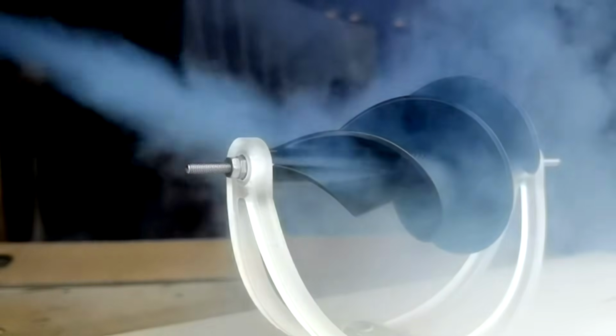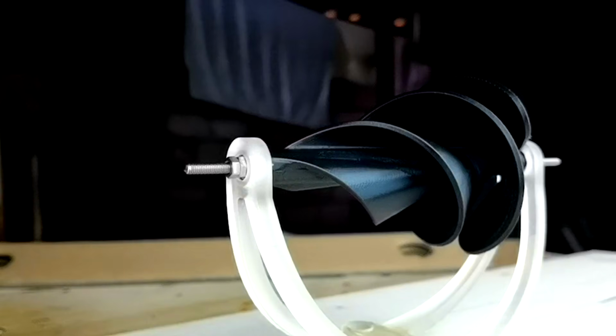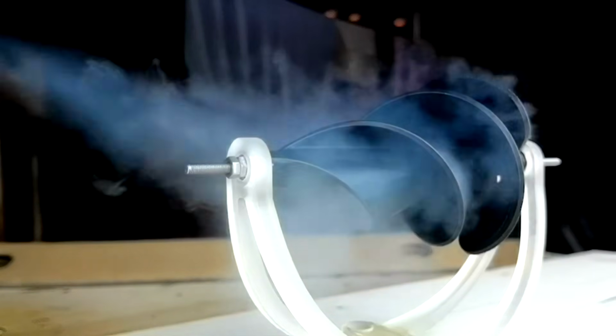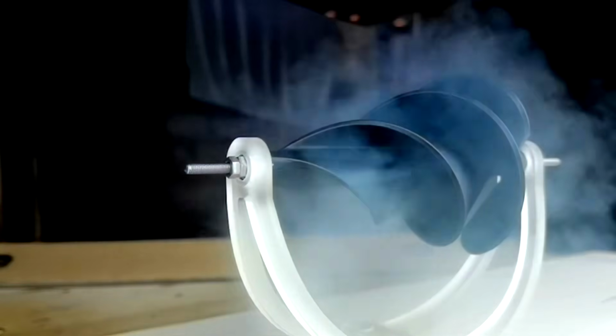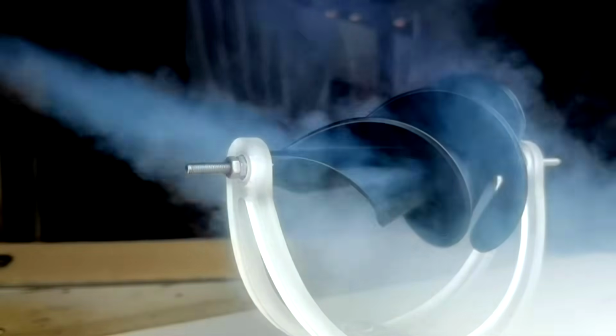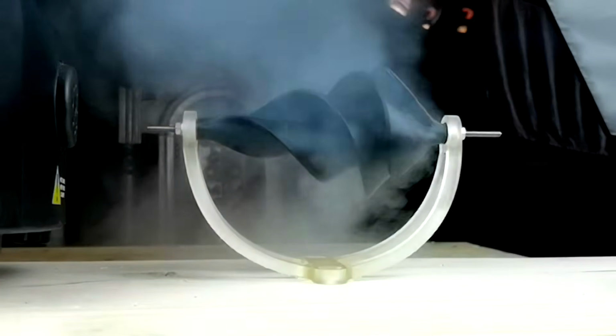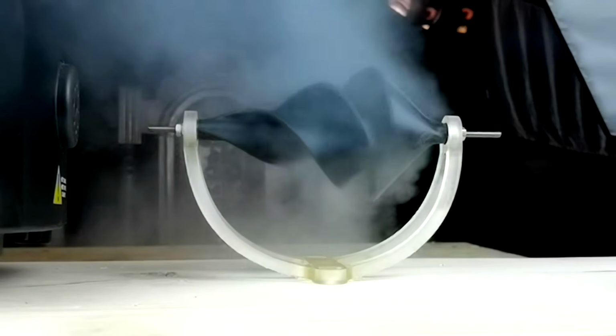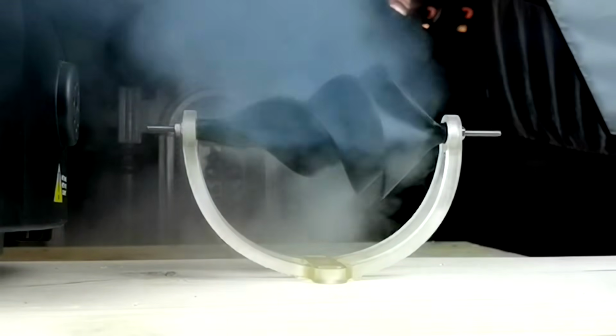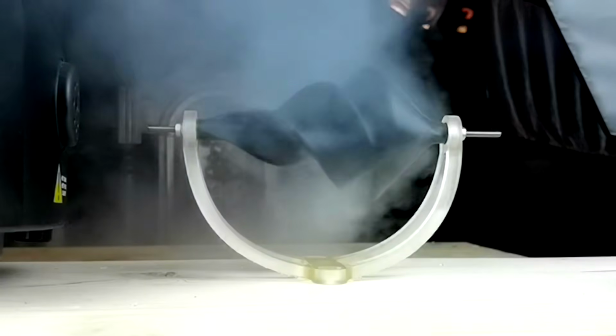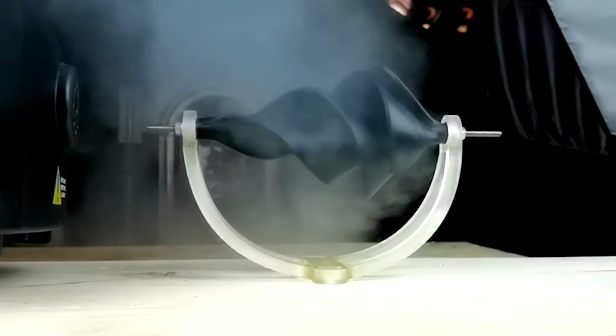The big difference here is the reversibility, because the Lily Impeller can also be used as a turbine. Instead of being the impeller moving the fluid, what about the fluid powering the impeller? Here you can see a small spiral turbine with a similar geometry to the Lily Impeller, being driven by smoke. As the smoke passes through the turbine, it changes direction gradually and loses most of its kinetic energy, which means the kinetic energy is going to the turbine.